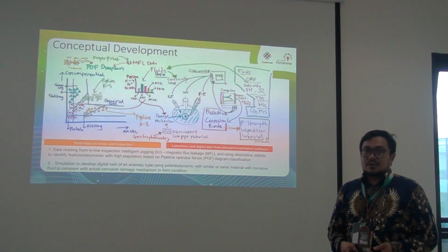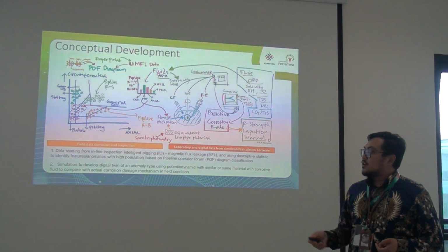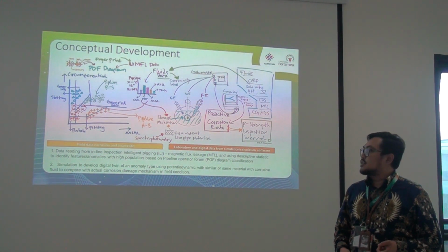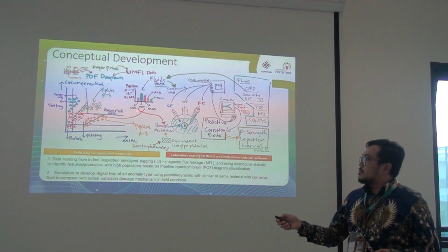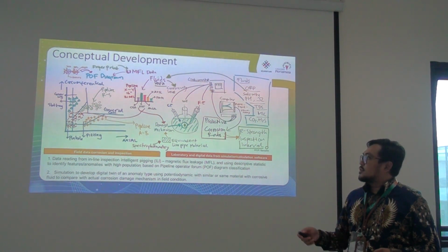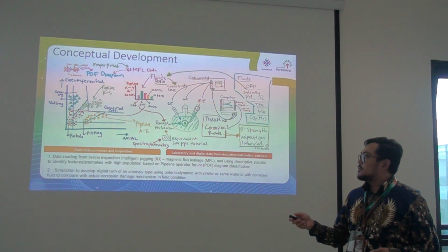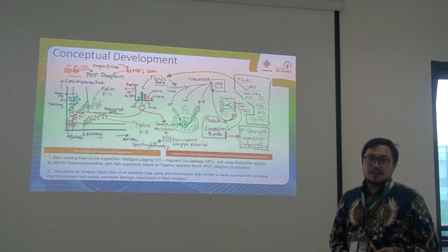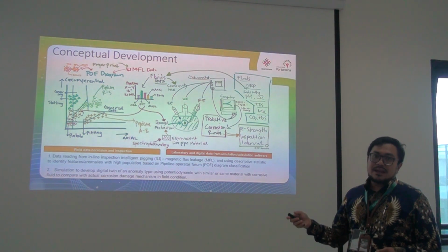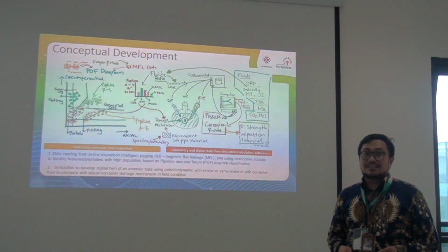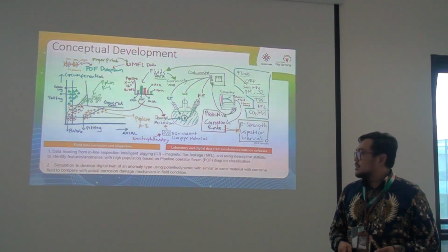This is the conceptual development for our research. We have different data and also the defect or damage mechanism condition from the ILI-MFL. We have the POF diagram. We compare the specific condition for circumferential grooving, let's say some pitting or axial grooving. We have samples of damage mechanism, and we identify them to make copies, or what we call the digital twin, for testing in galvanostat or potentiodynamic test simulation.